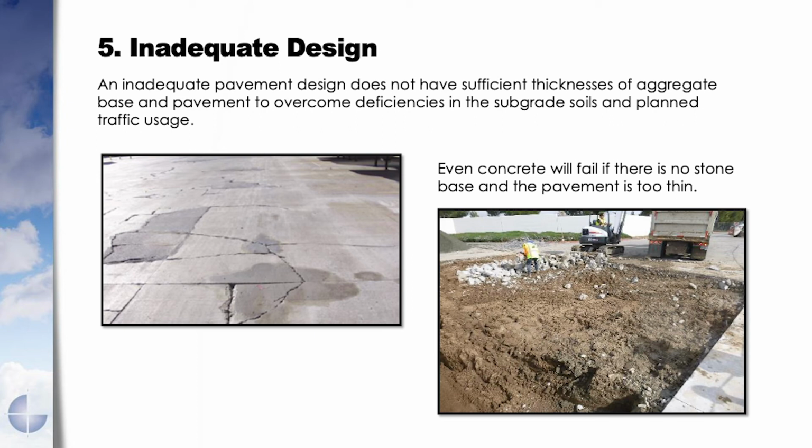In this case here, concrete was only spec'd at 6 inches deep. The cores actually showed that about half the cores were even less than 6 inches, so it wasn't even built to specification. But what's happening is the concrete was too thin to support the heavy loads of the trucks pounding over the top of it. And just like hitting a stone with a hammer in your driveway, that concrete was being hit by the tires and the loads, and that caused it to fracture and crack and fail prematurely.